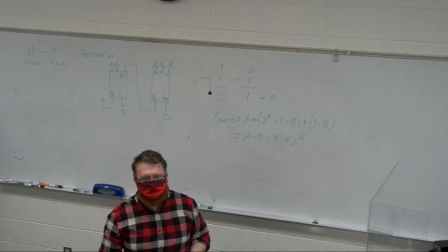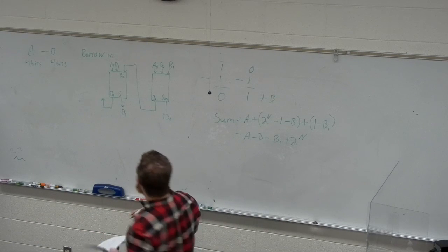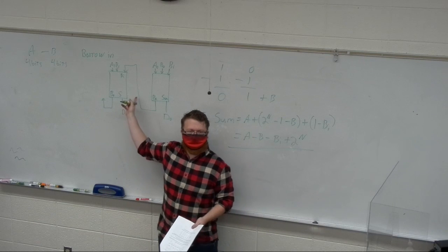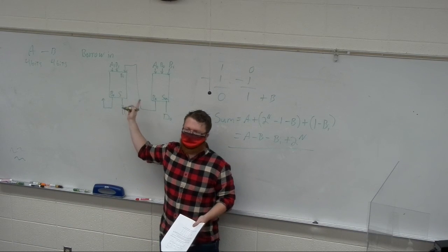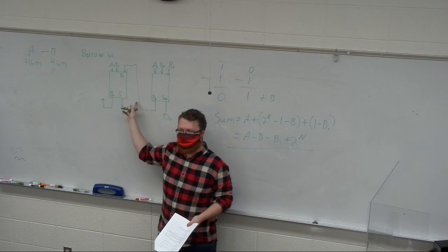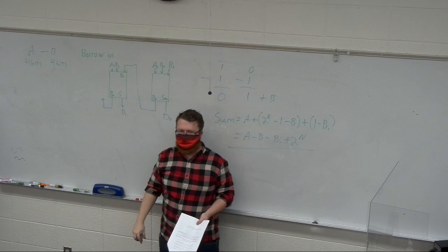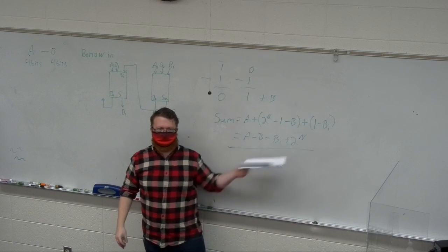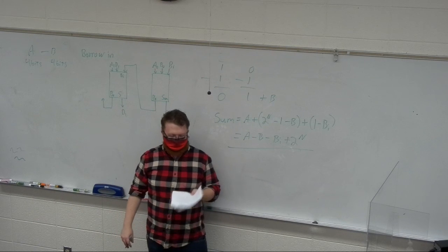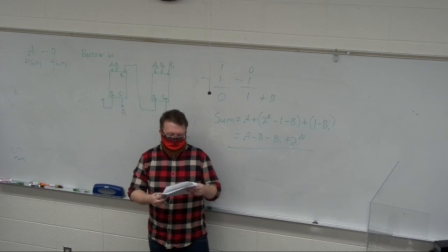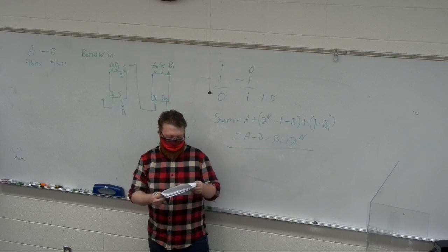We understand that. This is one of the cases where you don't have to understand the math to understand its usefulness. And that's what I want you to take away, that you can use a ripple adder to build a subtractor, whether or not you understand the mathematics of the thing. It will take you through the simplification of the K-map on the full subtractor because it is a little bit different.